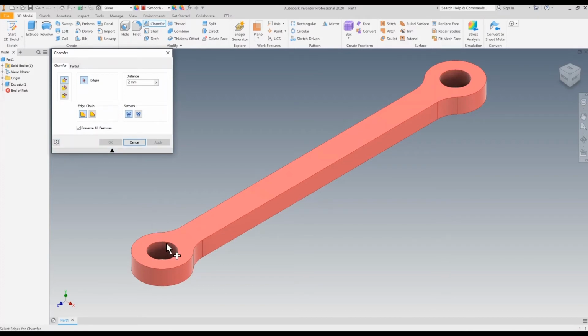It works quite similarly to the fillet tool, as in you just click your edge and it will chamfer it down. In this case, it's much too high, so let's drop that down, 0.5. That looks more reasonable. So this is just the distance. You can also change the way that this is calculated by looking at the angle and the distance, or two distances.